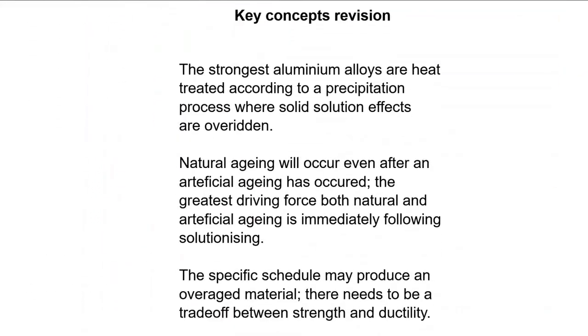So as we've seen, heat-treated alloys employ the elements in solid solution to age under carefully maintained times and temperatures in order to achieve specific properties, either an emphasis on strength or ductility. Even though overaging can reduce the overall strength that can be achieved, ductility can be recovered, and stability to the alloy can be restored.